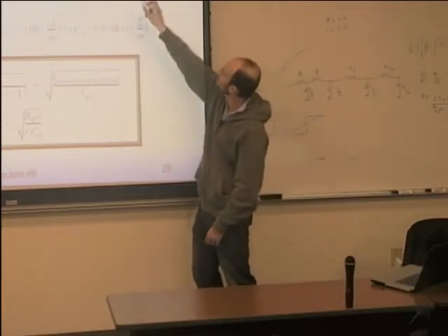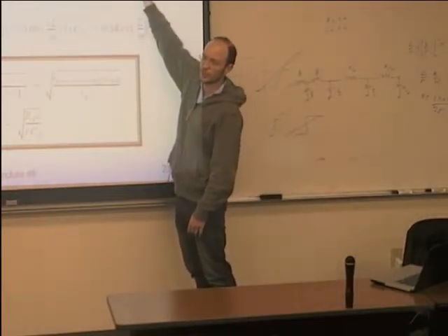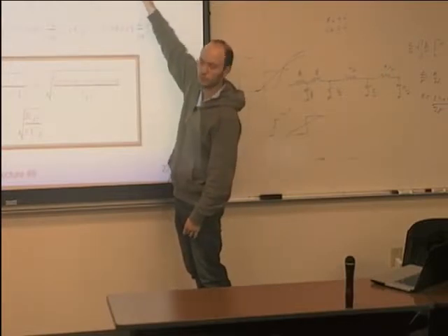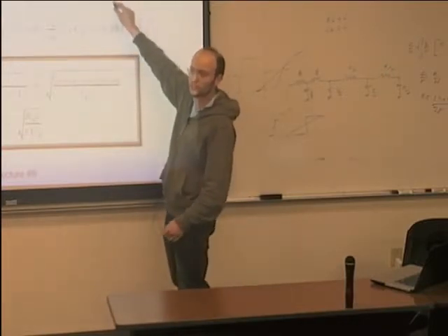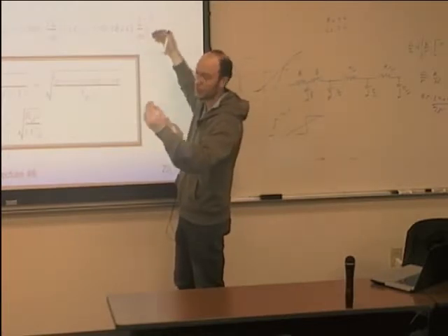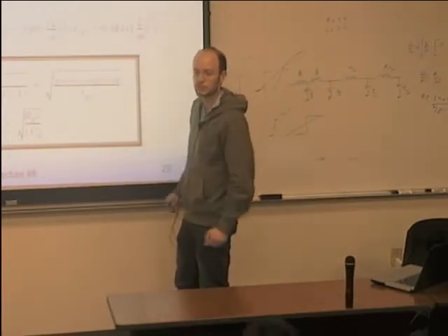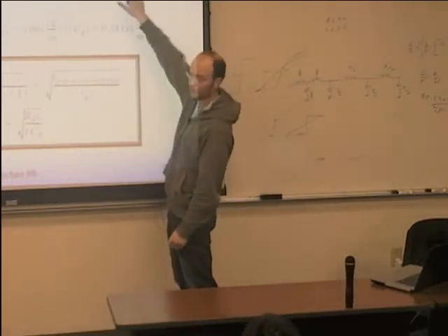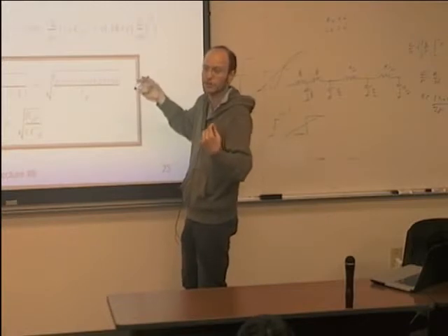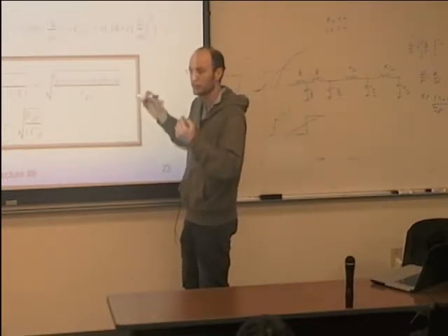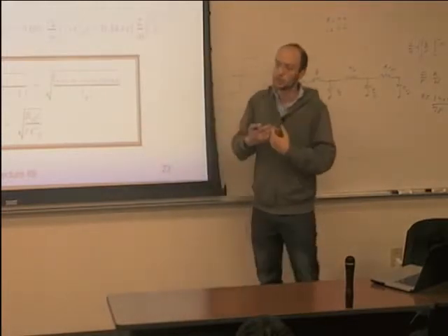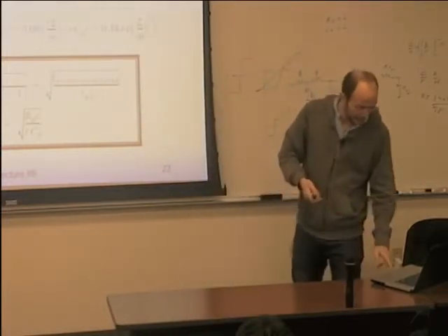And so if this wire is very slow, it's a high RC layer, then this wire will be short, okay? Which means that for a total length, there will be many, many sections, many, many inverters, okay? If this wire is fast, then this segment will be long, okay? And then there will be fewer inverters.